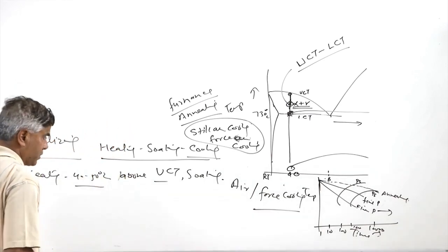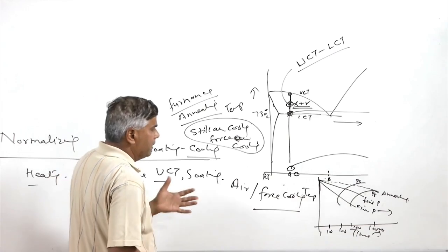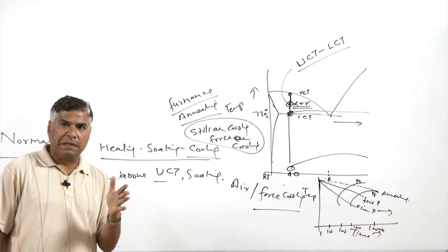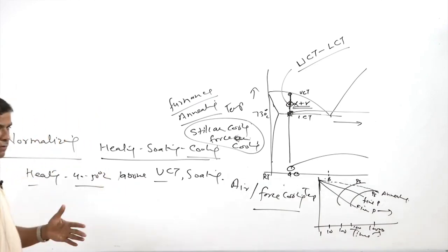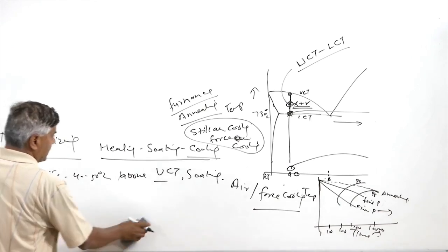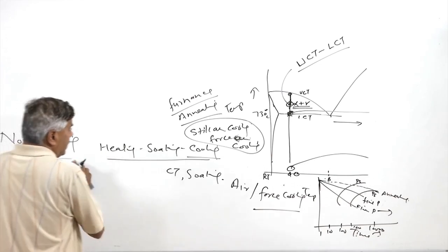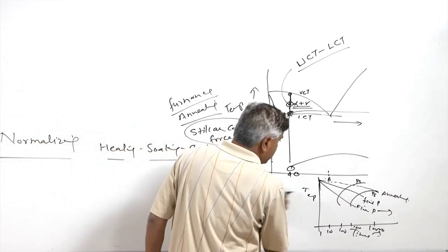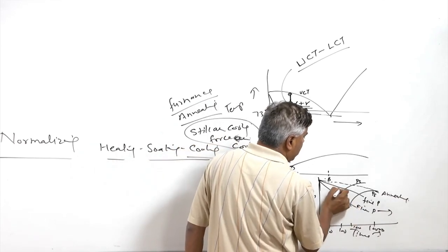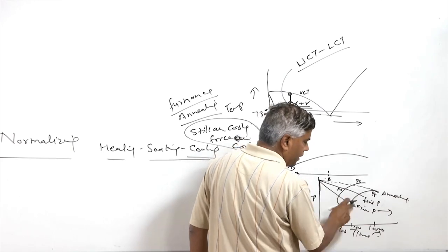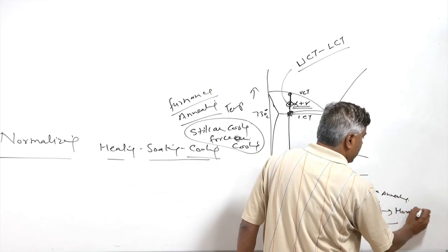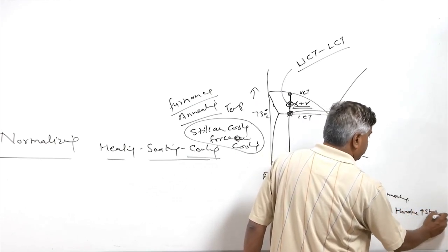At the same time, a very refined structure is also obtained, and refinement in the case of steels with regard to the pearlite is observed from the interlamellar spacing, like ferrite to ferrite or cementite to cementite distance. So with reference to normalizing, we use higher cooling rates, and using the higher cooling rate results in a finer grain structure, which will lead to higher hardness and greater strength.